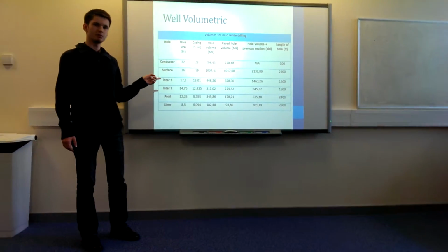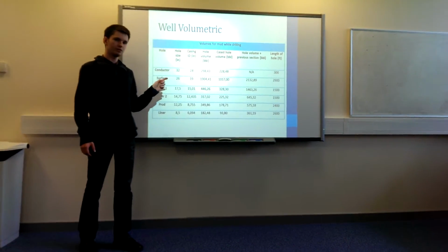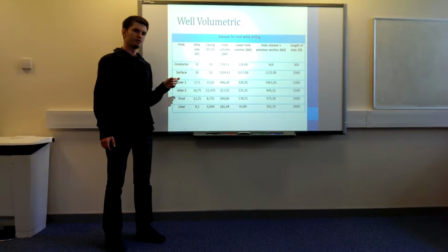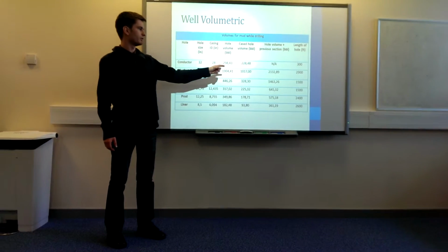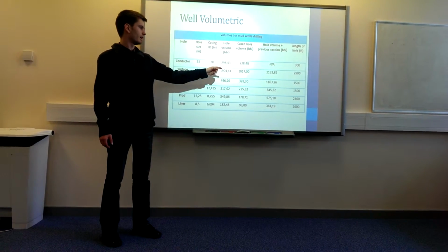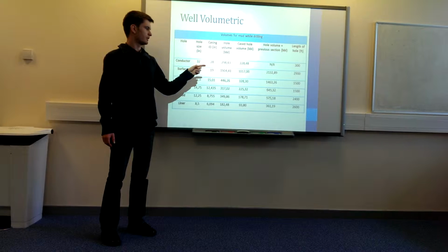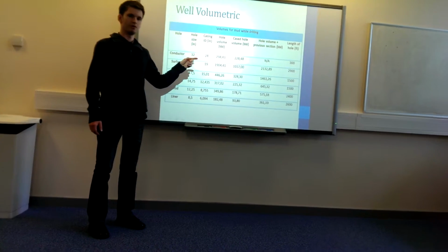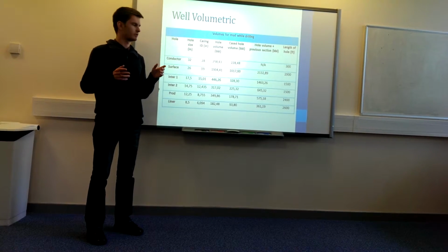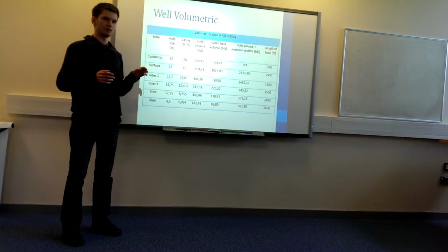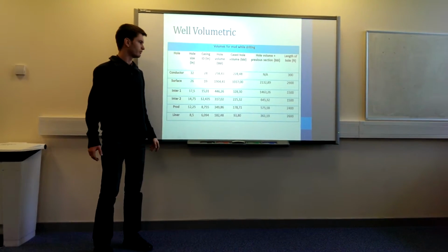And that gave me this nice table which identifies the volumes of the mud required in the well in each section, excluding the drill string. These values show that the maximum amount of mud required will be 2,132. During the next step, at the transfer from surface to the intermediate casing, we lose around 1,000 barrels of the mud. That means we will need maximum free storage for the liquid mud, over 1,000 barrels, to dispose of the mud and to carry on with our drilling operation into the smaller volumes.